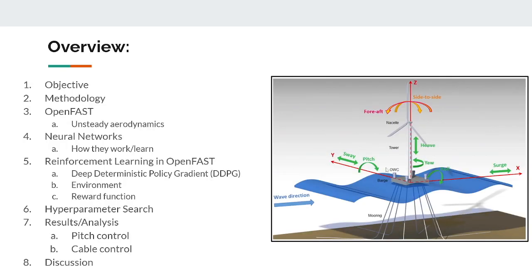So going back, we can see the pitch right here, which is the turbine tilting back around the y-axis, and also the roll, which is the turbine rotating around the x-axis. These create rotational forces on this tower base section right here, and these will be the forces that we are trying to minimize in the OpenFAST simulation.